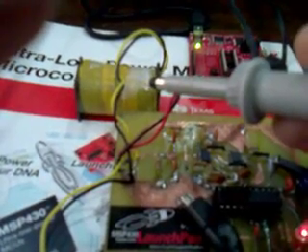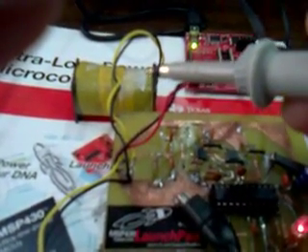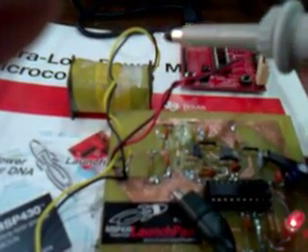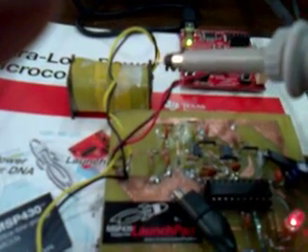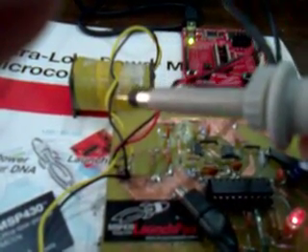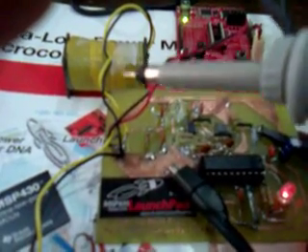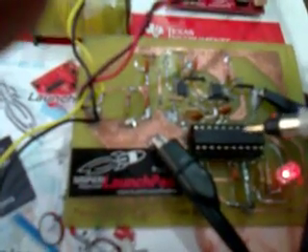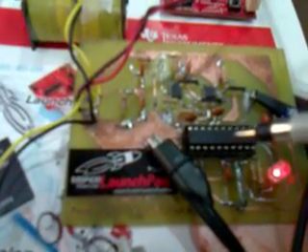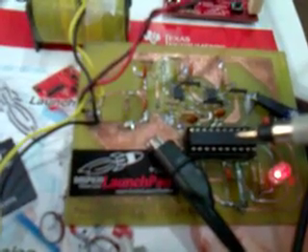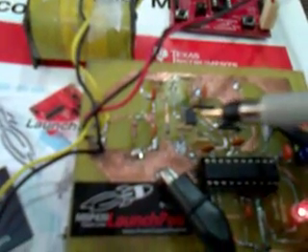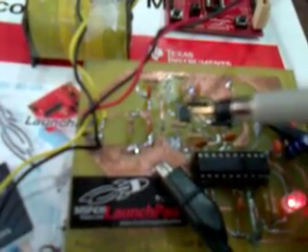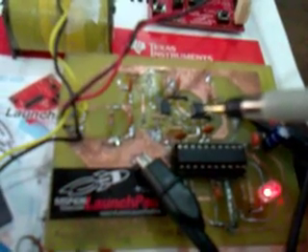This is an inductive current sensor which is placed near the MV overhead line, and it senses the alternating magnetic field produced by the current flowing through the MV overhead line. So it basically measures the current flowing in the MV overhead line. The output of this inductive current sensor is fed to the input of this sensor board, which is designed around the MSP430 G2553 ultra low power value line 16-bit microcontroller provided by Texas Instruments, and the signal conditioning circuitry is designed around the OPA2379 ultra low power dual op amp and the TLV3402 ultra low power comparator.